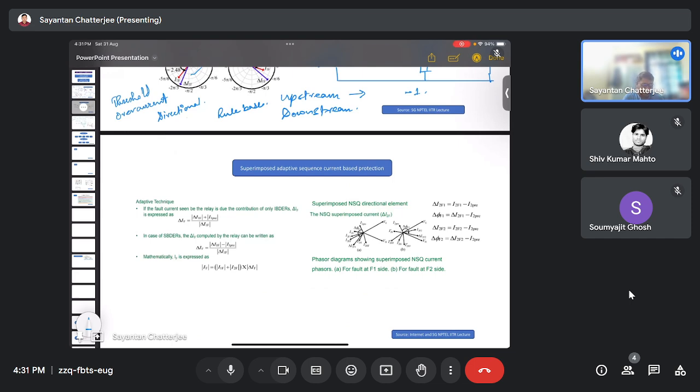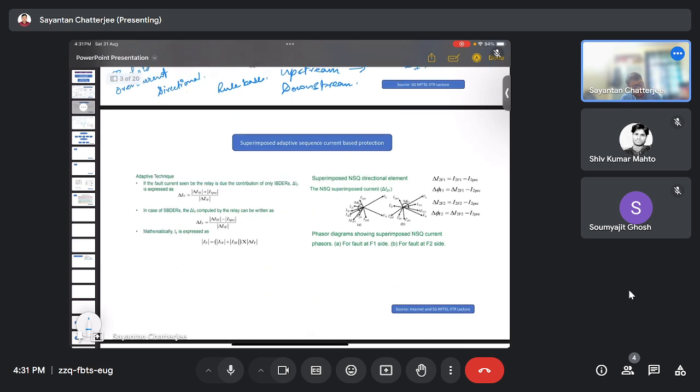So in these adaptive protection schemes, we have some problem, like synchronous based DERs impose a fault current of 5 per unit, whereas the inverter based DERs impose a fault current of approximately 2 per unit. So there's a certain mismatch amongst them itself, right? So to take care of this mismatch, we need to scale them down.